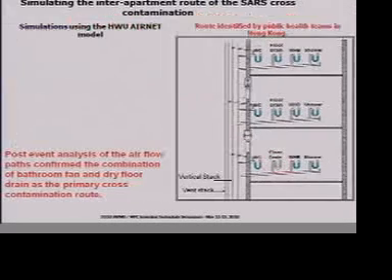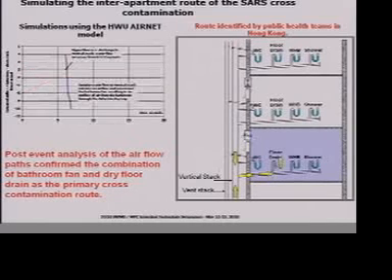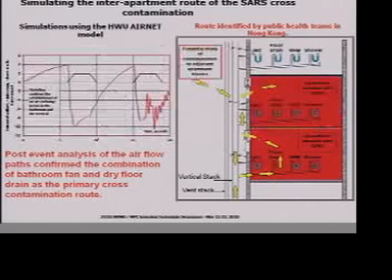So we can analyze what happened numerically using our models, and we can show that effectively we had an exchange of air between the space and the vertical stack, in that the fan moving sucked air out of the stack. When we have discharge down the stack, it sucked air back into the stack, and so forth. So in other words, that space was effectively breathing the SARS virus, which was coming down the vertical stack, because it's a highly diarrheal disease, and therefore the stack is a mist of diarrheal particles.